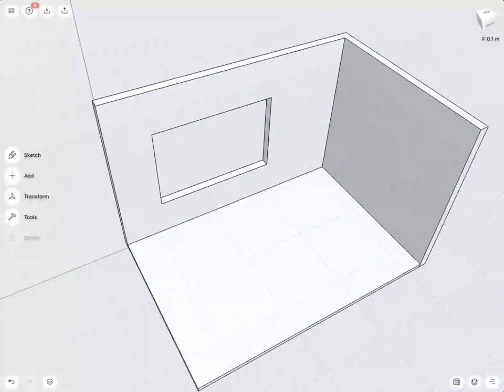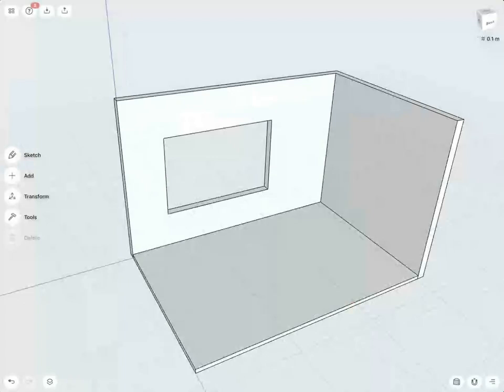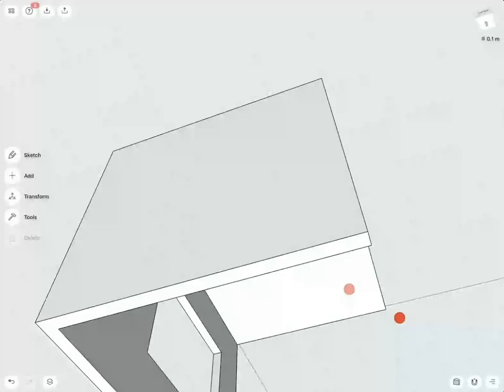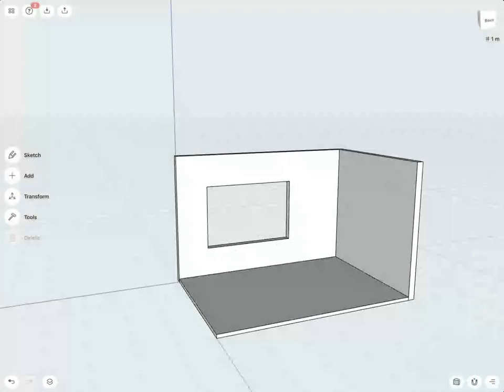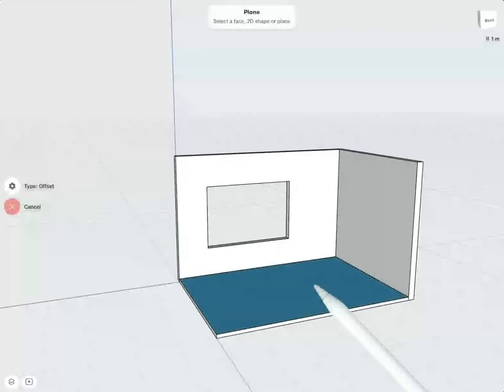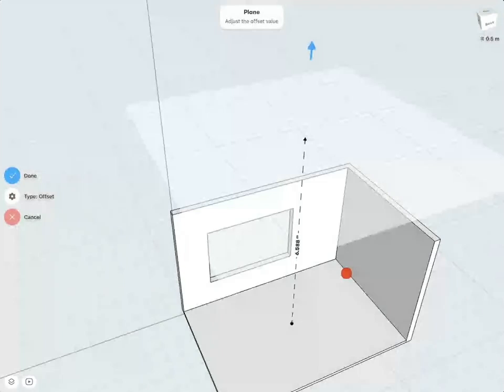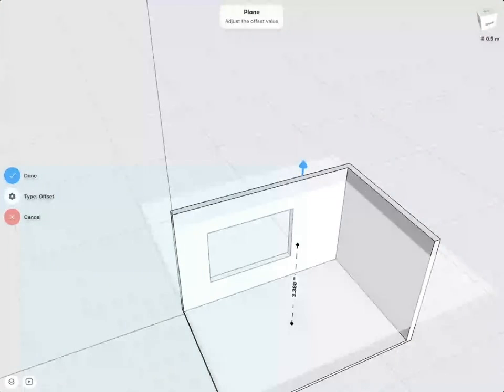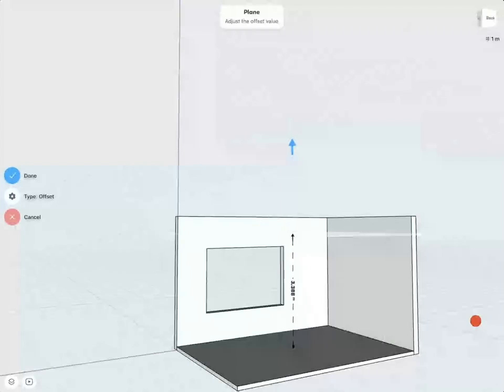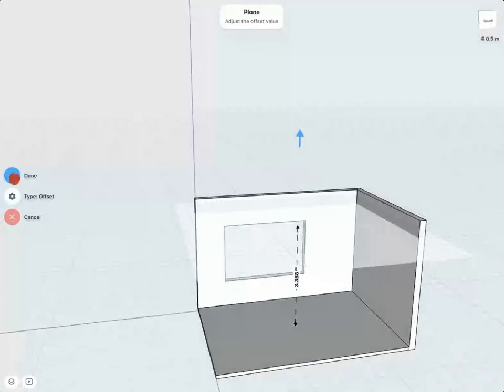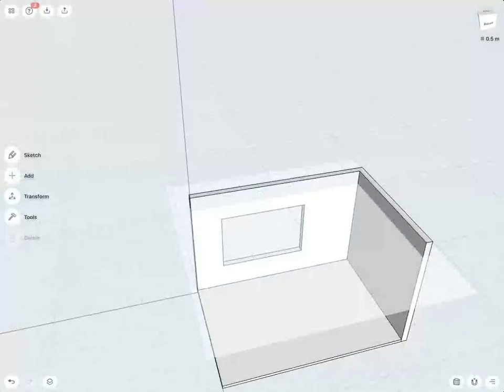To have the pipes kind of like where I had them before, I need to create a sketch in that area. So let's say we are in top view. You see that the grid is lined up on the bottom. To be able now to draw where I had the original pipes, I can go to Add, go to Construction Plane, select the ground, select Next, and then I could create a construction plane right at the height where, for example, I need it. Select Done. Very good. Now it's time to figure out from where to where do these pipes actually run.